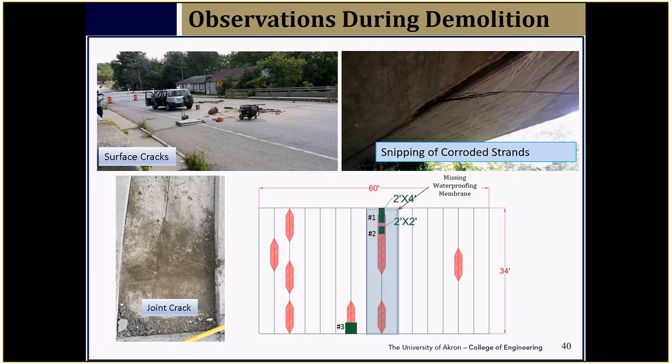I know. Sorry, Jim. I know. Right. Obviously, I've been somewhere they were smart enough to figure out logistically how you could get on one side and put the asphalt down. So we don't want the trucks backing up and forth on the membrane. So we place it in the paver, and then the paver goes out across the bridge. It's very rare that you can do that. There's much more to think about, but sometimes to get from one side to the other, it's a long detour.